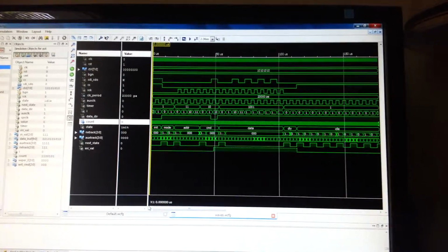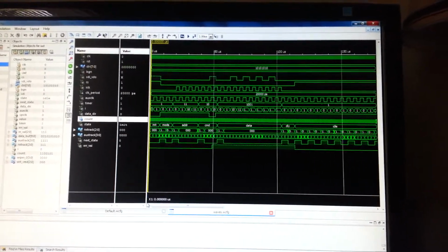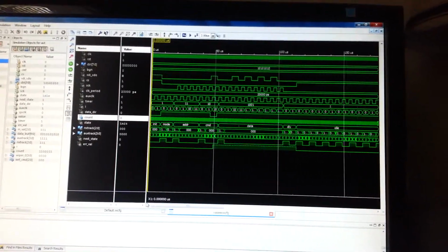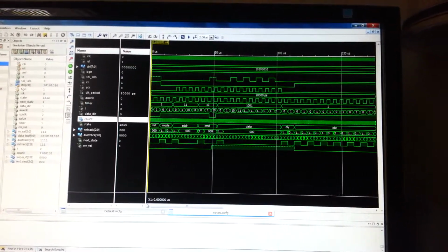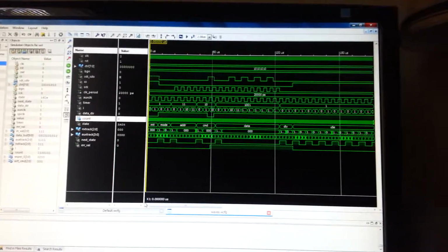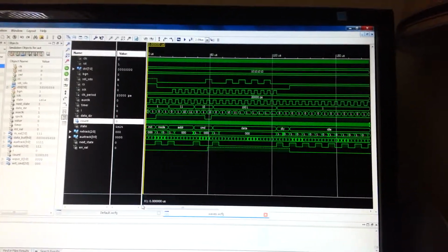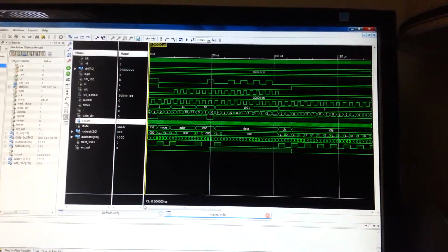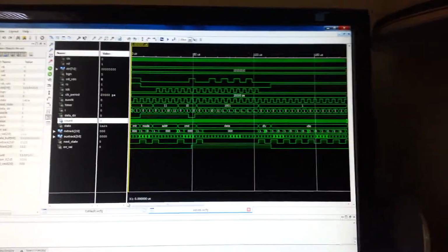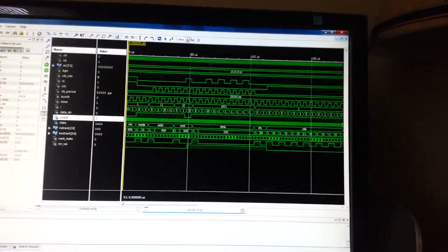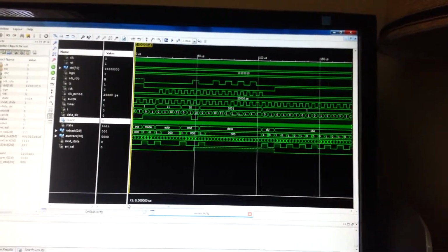Usually standard SPI has dedicated SDI and SDO lines. This one had an interesting interface, more like a hybrid, like I2C/SPI, because the SDI and SDO lines were on the same line. Internally inside the device, it's multiplexing when an input and an output is occurring.